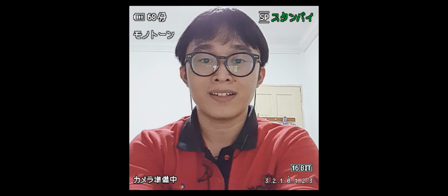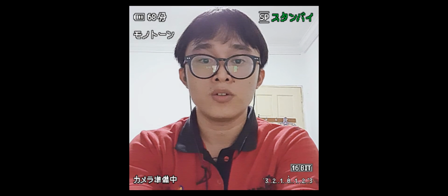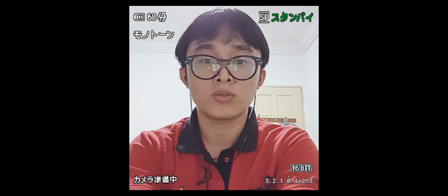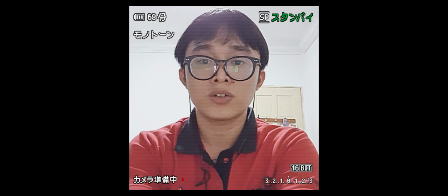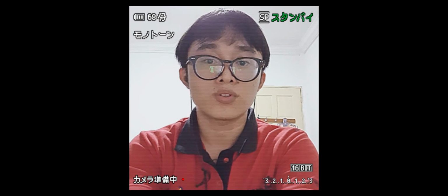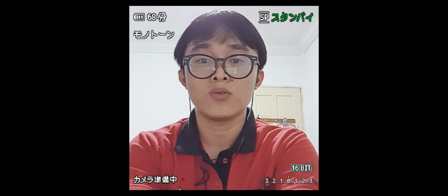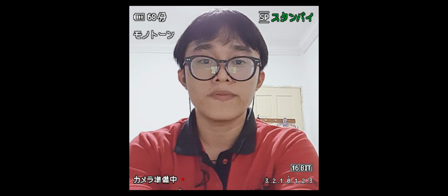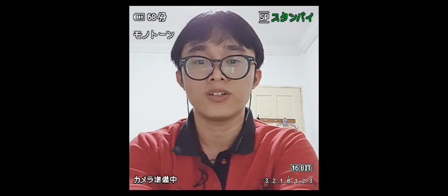Nur Adli bin Hatta, the video editor for this group. The bottom line is, when analyzing data, histograms are often used with statistical process control, SPC, control charts. That is, the same data used to create a control chart can be used to create a histogram. While control charts display data in time sequence, histograms do not. Instead, histograms show individual data values summarized and compared to engineering specification.